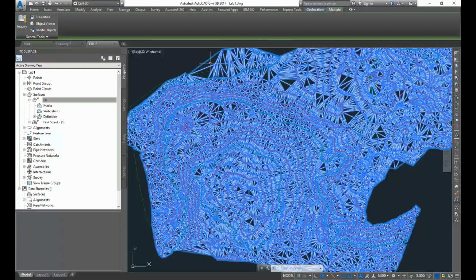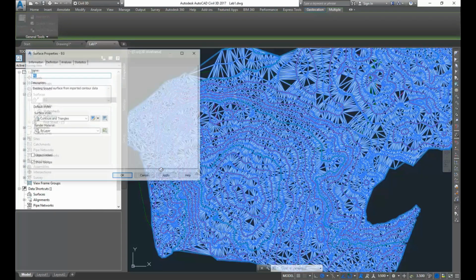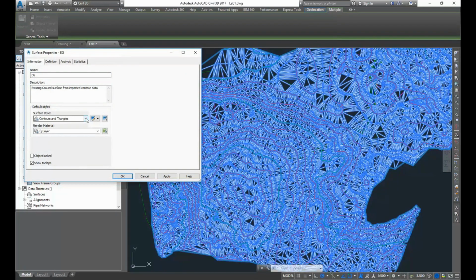So there could be a big hole or a mountain or something that we didn't see, and it would just straight line interpolate between the elevation here and the elevation there. So we might have less confidence if we were designing some sort of drainage structure out on the fringes. It's good to know what the TIN looks like, because it gives you confidence about your survey data.